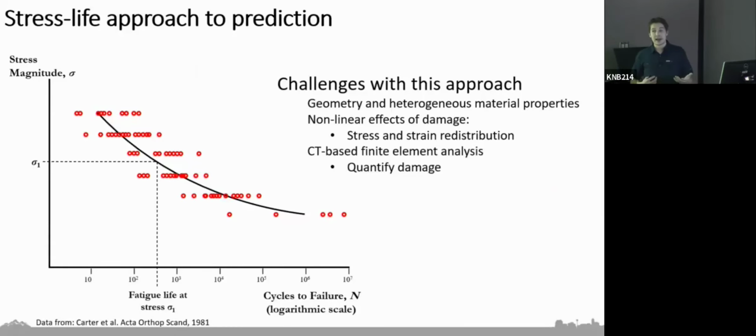So when I've been talking about damage this whole time and using this damage fraction where we can actually count up those cracks and voids and take that damaged area, well, this is kind of a histological approach, and we can't exactly do that, particularly if we're trying to predict stress fracture. We couldn't do that to human bone if we're trying to make these predictions. And so we developed a continuum damage mechanics model to actually compute that damage, and we use a strain-based damage model, which we'll go into depth on a little bit later here.